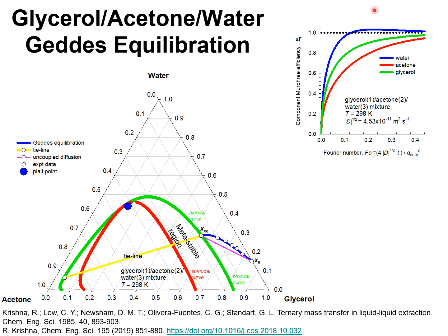In other words, the departures from straight line equilibration is to be attributed to differences in the component efficiencies, and the curvilinear equilibration paths may cross distillation boundaries. For liquid-liquid extraction, they may also enter the metastable regions and cause emulsification.